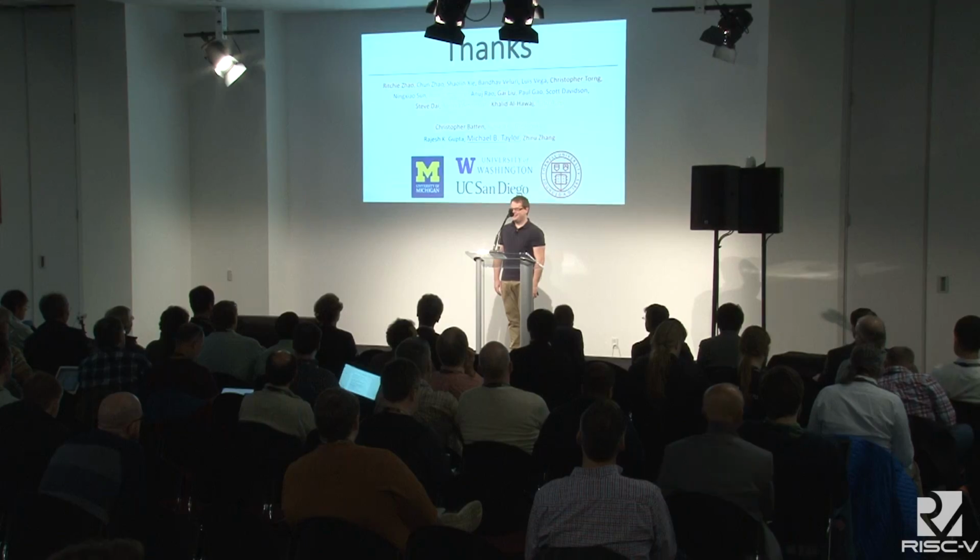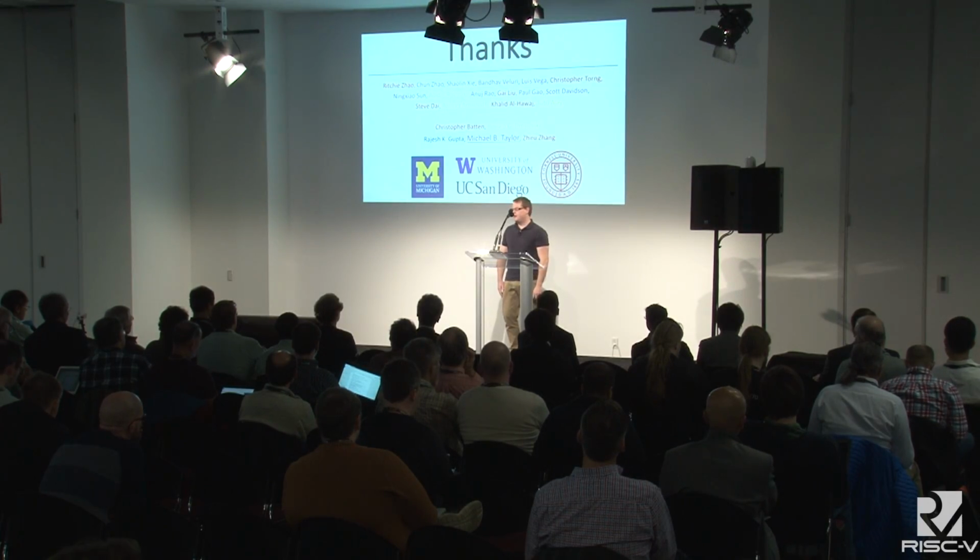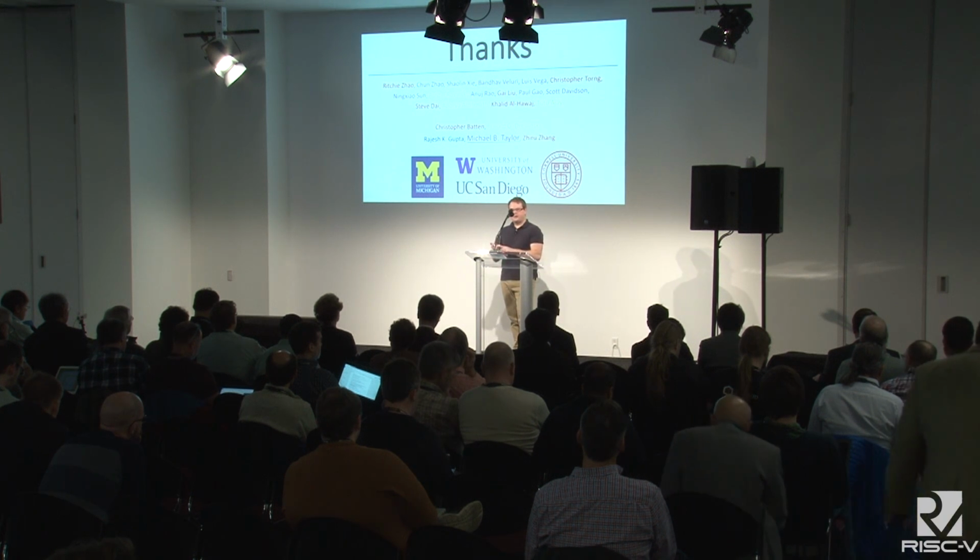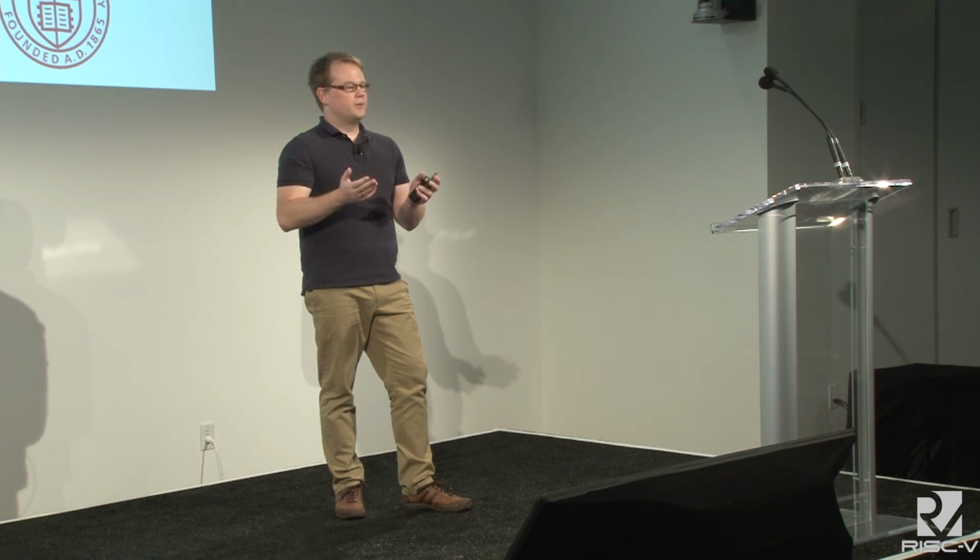Okay. So the question was, what about clock domains? What about DC-DC converters? Did I miss anything else? Oh, and how many? Okay, yeah. So we have a separate clock domain for doing off-chip I/O. We have a clock domain for the Manycore, and then we have another clock domain for everything else. And then for each clock domain, we have a PLL. The PLL is actually also open source. It's actually all digital implementation using standard cells. Okay? It was designed by a faculty member at UCSD, Ian Galton.